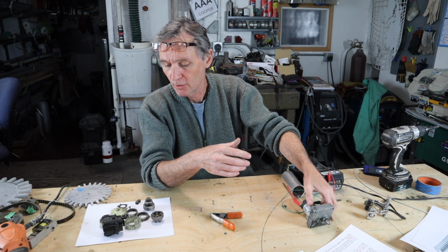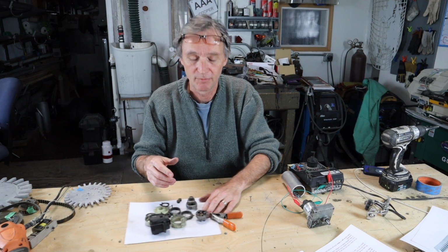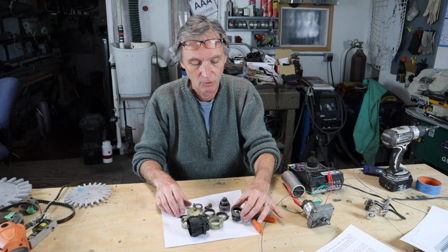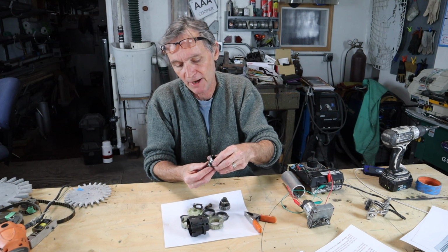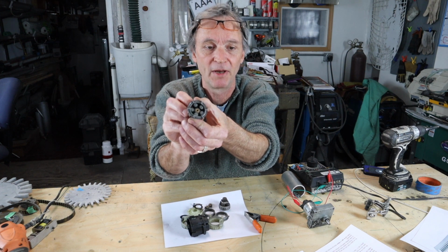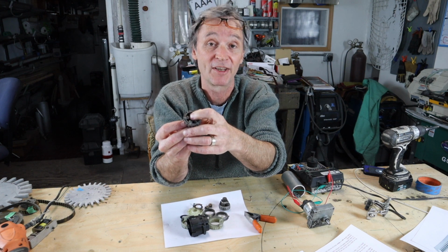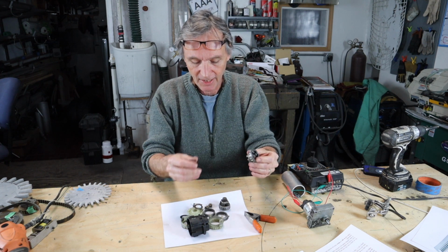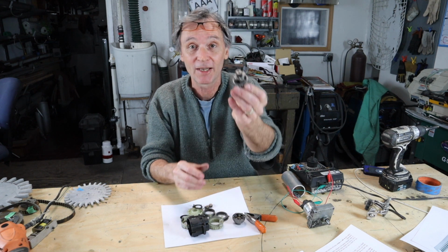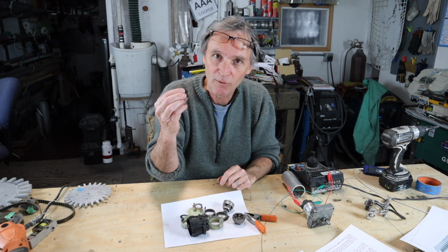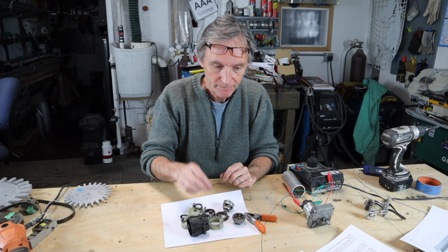So there are also planetary gear sets if you want to reduce your speed even more. Whoa, I'm going to spill these. These came out of a Makita. You can see they all spin around. The one in the middle is called the sun gear, and then the planets around the outside, just like the solar system. These things, when you take them apart, good luck getting them back together again. There are a lot of very small parts that only fit in one very exact way.